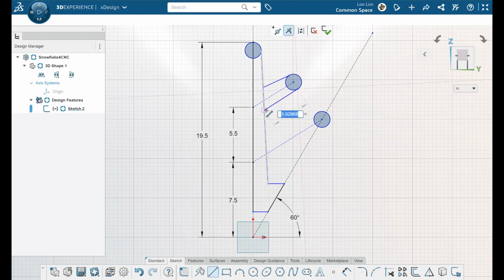I'm creating the shape of the spurs coming off of the main leg, again using L to turn on the line, Escape to turn off the continuous segments. I'll do that for both of my legs. I'm taking time to make sure that when I begin a line and end a line, I'm catching a coincident mark. That's what the little pink circle is. Now I can go back and make sure that all those connections with the circle are tangent.